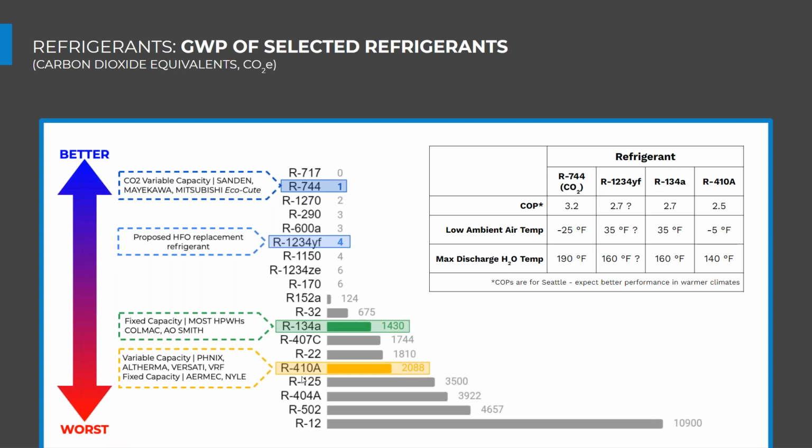There's a large volume, and we need to be very aware of it. It's great that in these heat pump water heating systems, we typically have packaged products where piping has been done in a factory rather than in a field like a VRF system. So our R744 is our CO2, and that's what the scale is based on, so that's a 1.